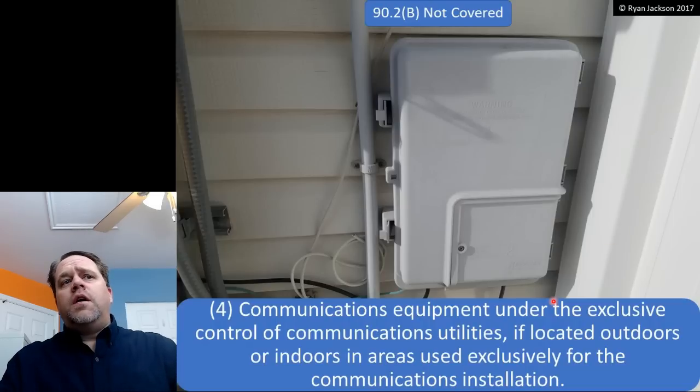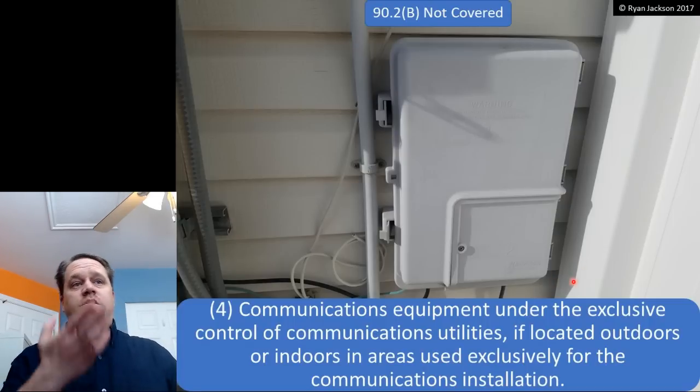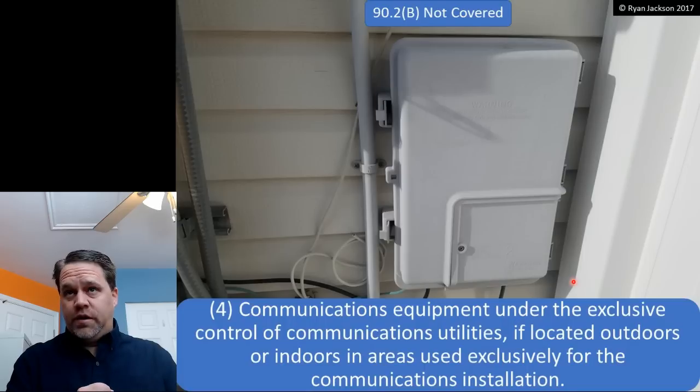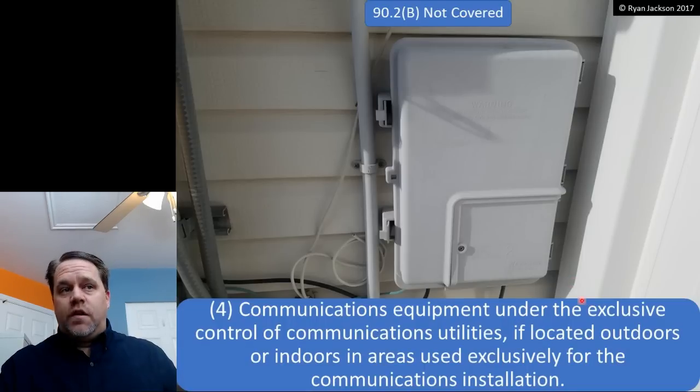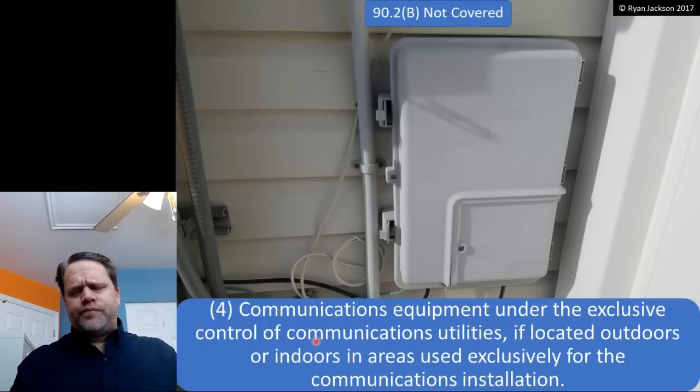So looking at this photograph, this may or may not be covered by the NEC. I know it's not because I took this picture and that's at my house. And that's Comcast that put it in. They are a communications utility. That equipment is outdoors. It's under their exclusive control, so it's not covered by the NEC. If I were to install it and I had control of it, then it would be covered by the NEC.